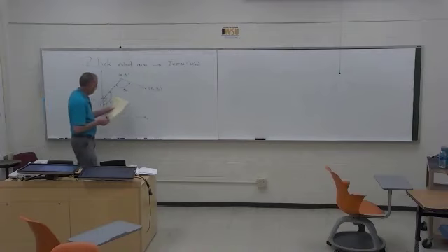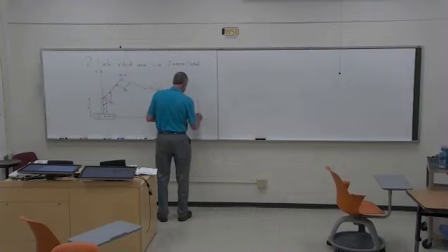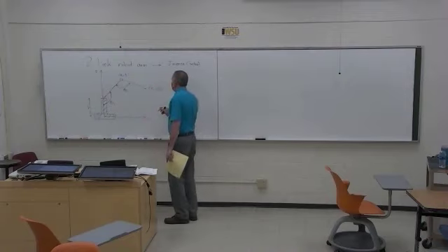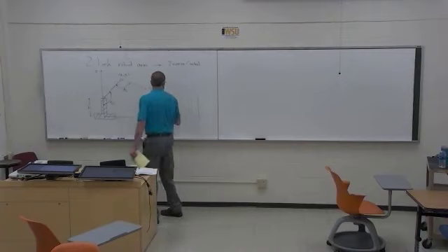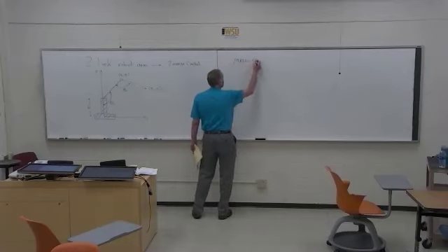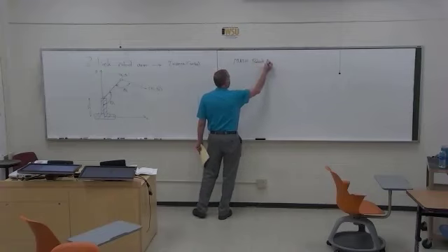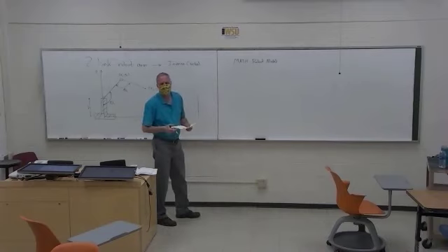So let's go over here and draw just kind of a stick figure, because what we're going to do is develop equations for x1 and y1, x2 and y2 as a function of θ1 and θ2. So we're really going to do a math model of the robot. So that will be our robot instead of actually physically having it sitting here in the room.